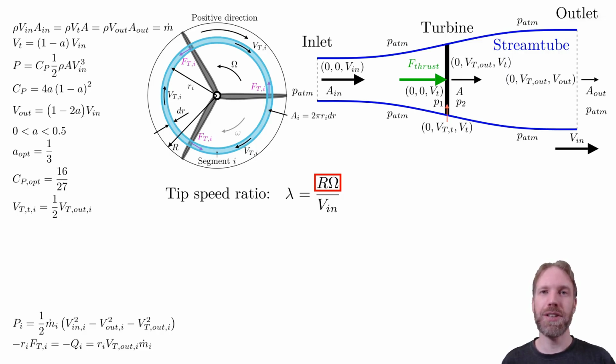Hence, the tip speed ratio is the speed the blade is moving with divided by the inlet speed. So how many times faster than the incoming wind the blade is moving. This is an important design parameter for a turbine because a real turbine will have a tip speed ratio which gives optimal performance. The optimal value will be relatively independent of the incoming wind speed.